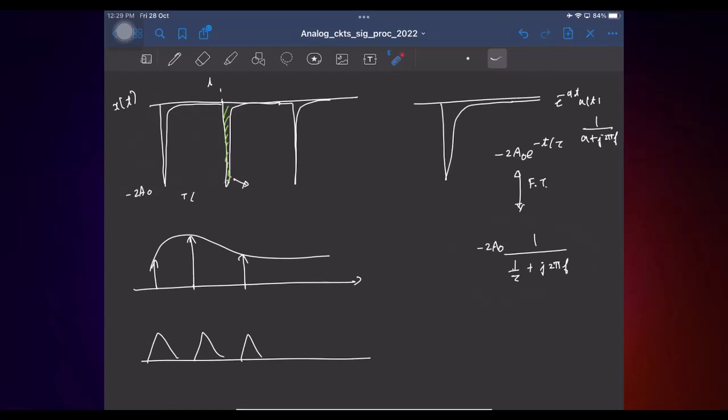So here you have periodic copies in the time domain, which means in the frequency domain it is as though the spectrum is being sampled. Is that fine? As he pointed out, the Fourier series coefficients, if I call this X of f, are a sampled version of X of f, but what frequency should I sample it at?